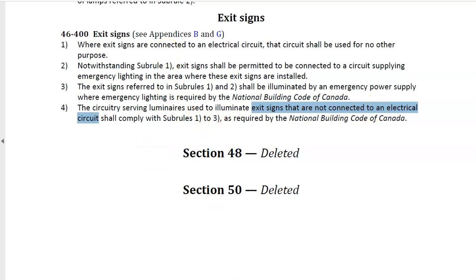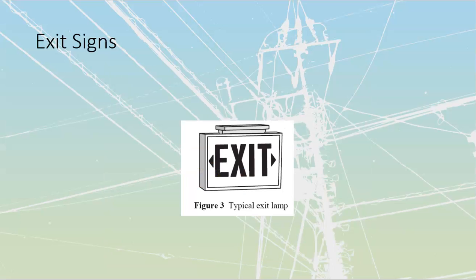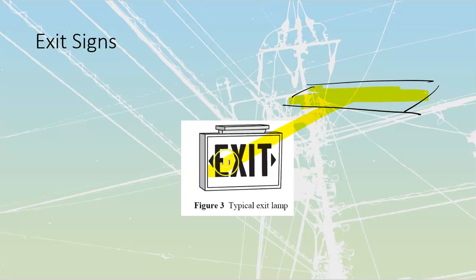What they're talking about specifically is that if I have a glow-in-the-dark type of exit sign, it's in an institutional setting, so we're just going to go with the assumption that we've got a troffer inside of the T-bar ceiling. The light that is closest to this is always going to be charging it up through the photons that are bombarding that surface. Because that light is necessary for this exit sign to operate, that specific light, even though it's a hallway light, can be connected onto our exit lighting circuits.